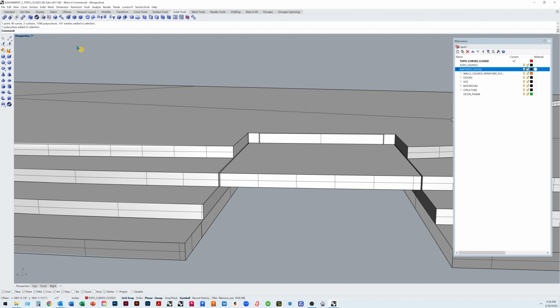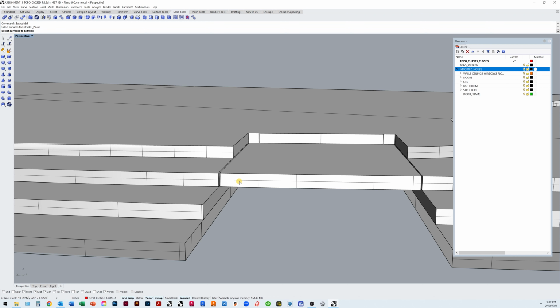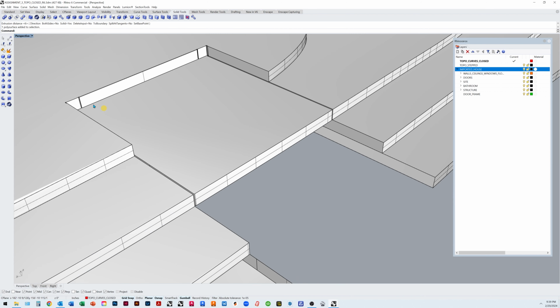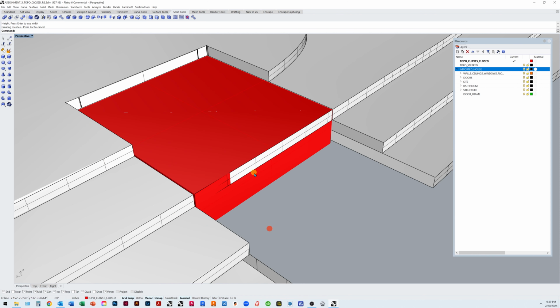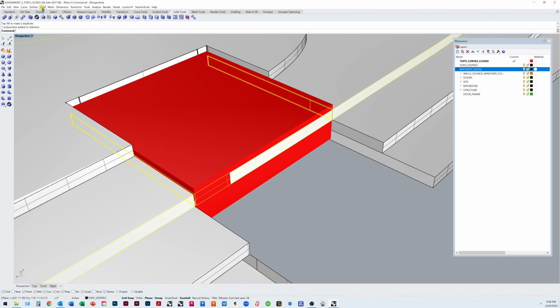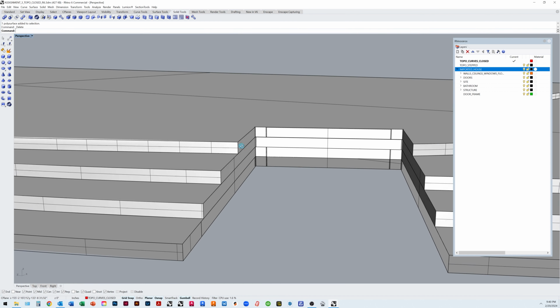We can extrude a surface. It's one of the nice ways to work on an angle. So if I want to extrude the surface, nope, not that one. We can come in and actually, this is one thing I do a lot, is I build a box and I use it to get rid of something else. So I'm going to build a box on top of that layer, and then I'm going to use it to difference. And that should get rid of most of these layers.